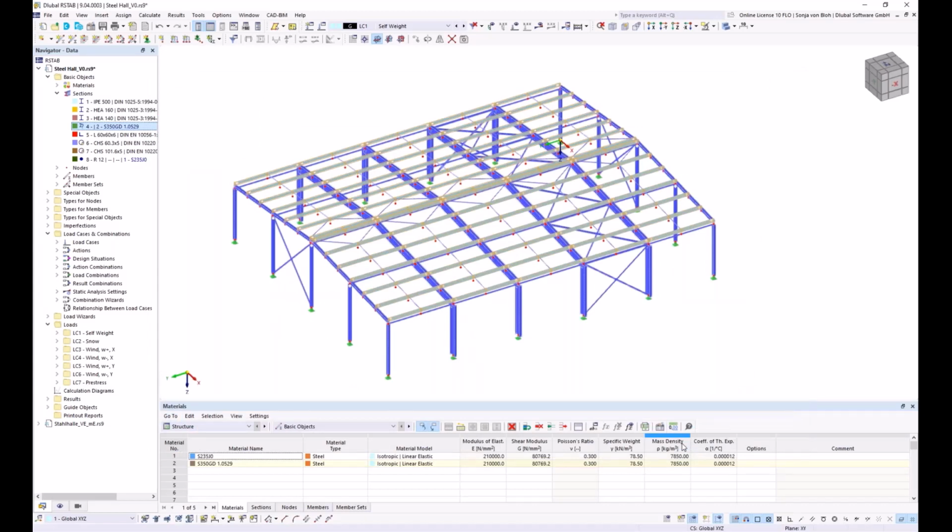For cold-formed cross-sections, the center of shear lies outside the cross-section and the main axes are rotated. Usually the loads don't act on the shear center, which results in double bending and torsion. Usual lateral torsional buckling checks cannot be carried out. Eurocode 3 Part 1-3 includes design methods for cold-formed purlins, but the purlins must be within certain limits. These simplified design methods are not implemented in steel design. The lateral torsional buckling of any purlin can be carried out according to the second-order theory, considering warping torsion and the use of equivalent imperfections.